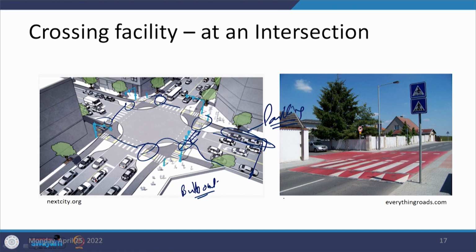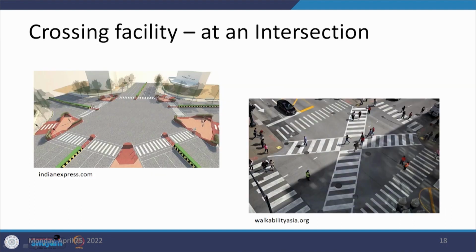Okay, so this is how we are going to provide the facilities, but in this case we are coming to the carriageway level. But if we talk about another one, here the level of the footpath is this one and the facility has been maintained at the same level. That is where there is a slope on this side and a slope on the other side for the vehicular traffic to get up and down, and this is 1 in 8 as a slope being provided. We look at another such orientation.